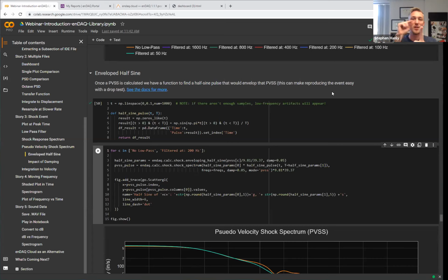It's impacted by just where you catch the event. You could have the same sample rate, the same event, and get two completely different peak acceleration levels just based upon how the samples lined up with the actual shock. It's going to lead to more confusion and conclusions that may be misleading. I really strongly encourage people not to do that.